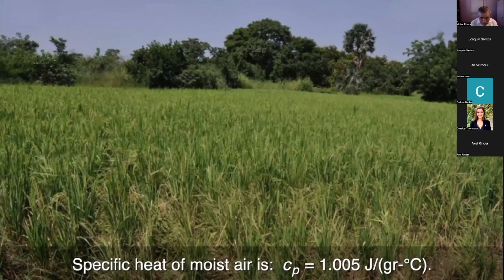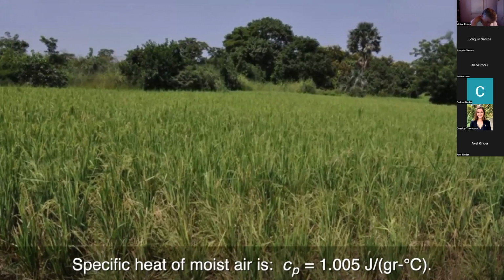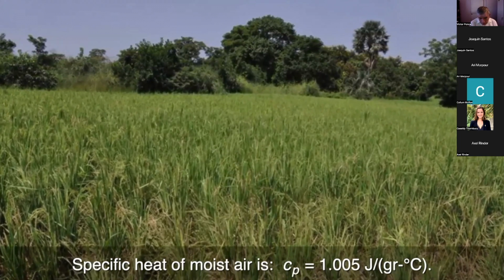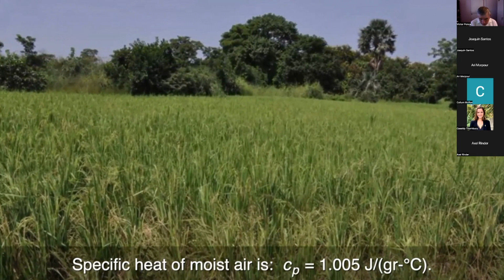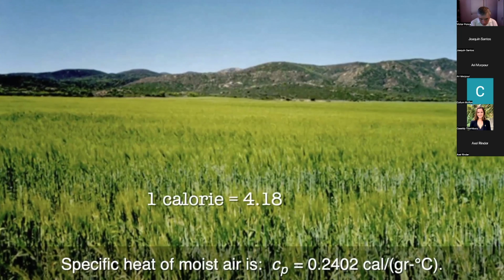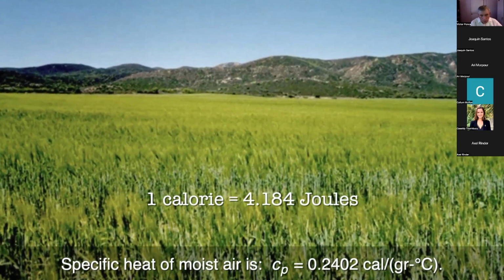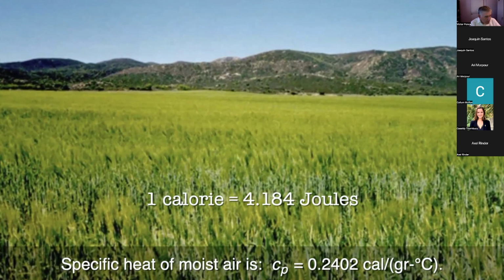The specific heat of moist air in the temperature range from 0 to 40 degrees Celsius is C sub P equal 1.005 joules per gram per degree Celsius. Converting to calories, C sub P equal 0.2402 calories per gram per degree Celsius.